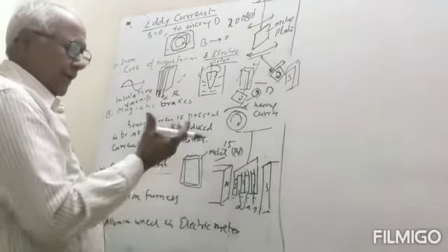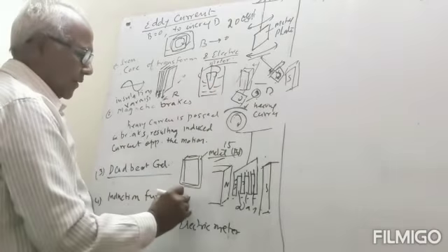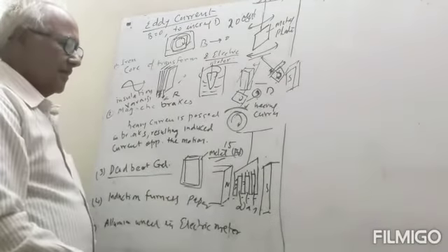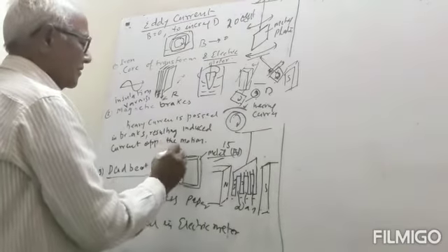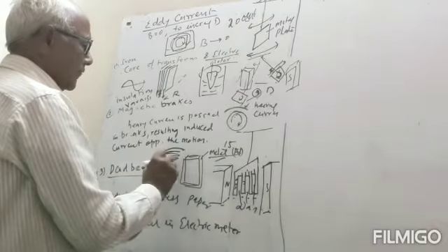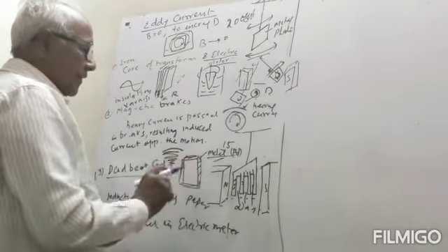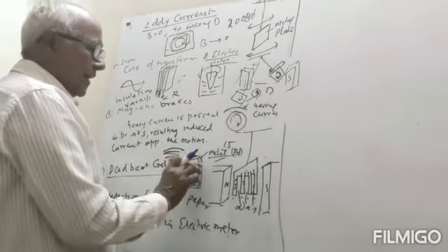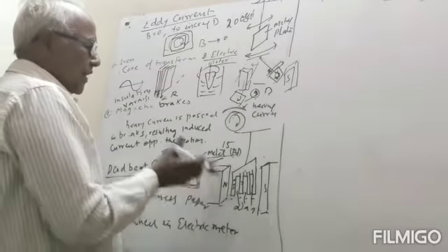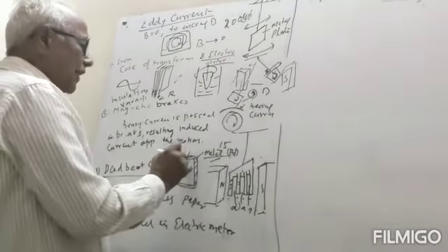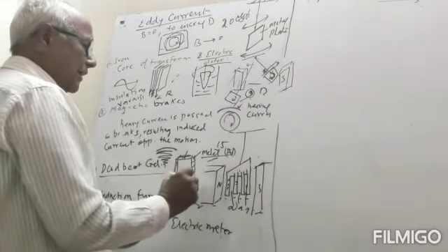So when it rotates, if this frame is, suppose, a paper frame, then the needle will oscillate, and after some time it will stop. But if we take a metallic frame here, then when it moves, the magnetic flux changes and induced current is produced, eddy current is produced, and it will oppose the motion. So it will stop just as, and we will get the constant deflection.